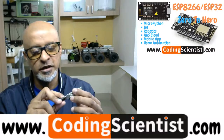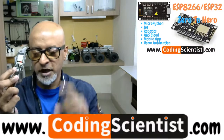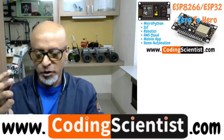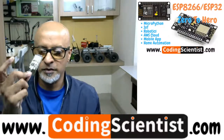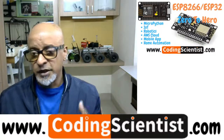The boot button, it's written clearly, boot button. So press that, hold it tight, do not leave it, and then click on the IDE to upload the code. And as soon as you see at the bottom it's uploading with the red color dots, then you remove your finger, right? And then what we tried to do was we were trying to scan.